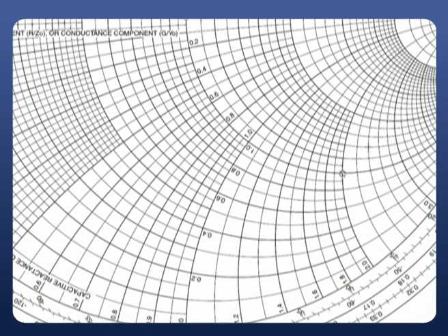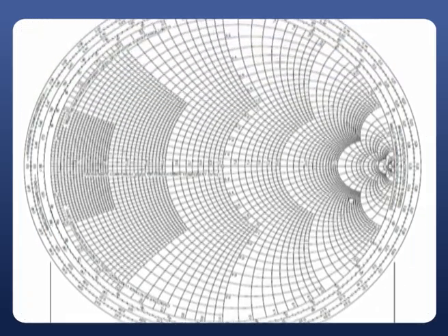This is a very important and basic point related to our Smith chart, that whenever we are considering a Smith chart, you are supposed to identify where the given impedance is. Whatever it may be, that may be load impedance or that may be our input impedance. If you are identifying load impedance, imagine that you are at the load. If you are identifying input impedance, imagine that you are at the input, that is nothing but our generator. So depending upon the conditions, you are supposed to calculate different parameters.